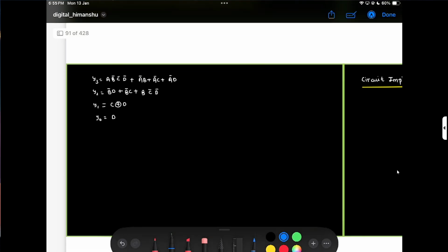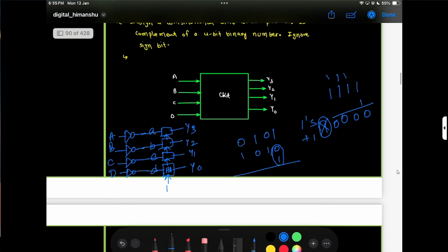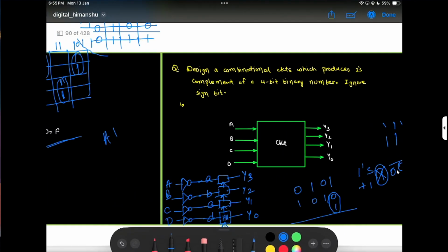Basically, if you know about how to make an adder circuit, this problem is actually one I did previously, that is, make a circuit that can do both subtraction and addition. So we just use a mux. So choose the negative. Suppose for addition, I want a plus b. So what we did is a is directly put into the full adder, and here is a mux, and b is like b.